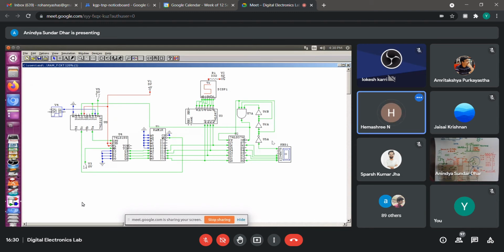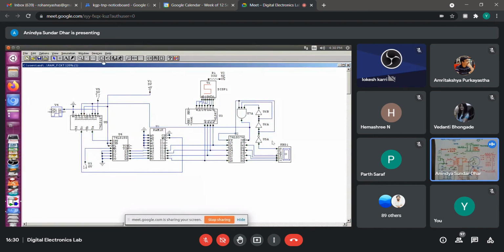Yes, sir. Okay, so this is something where it has been done manually. Let me just see whether I can make out what I did. First of all, this arrangement, I think you can understand, is for the strobe signal: inverter followed by 2 buffers and gate. I am getting a wider pulse over here, so I'm feeding that to this pin.